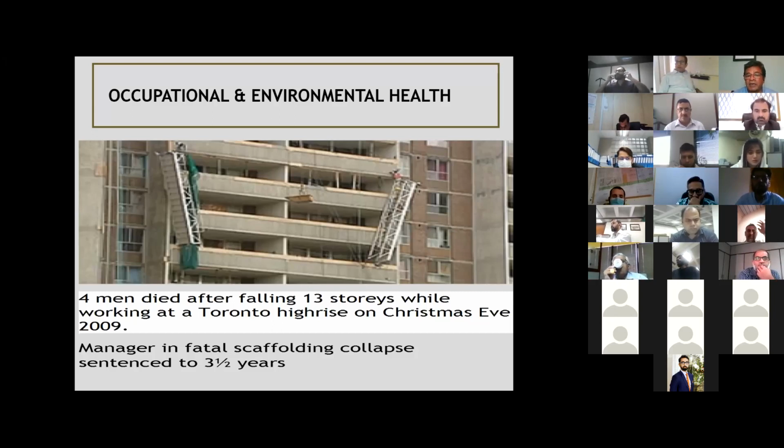This hanging swing scaffolding just snapped right from the center. There were 4 workers. They might be standing right in the middle of the scaffolding, not tied to any hooks. The scaffolding is still hanging, so that means the roof anchors were good. The roof anchors were holding this scaffolding. The other thing is that it's a building code that roof anchors have to be verified by a professional engineer after every 2 years or 3 years or before use.